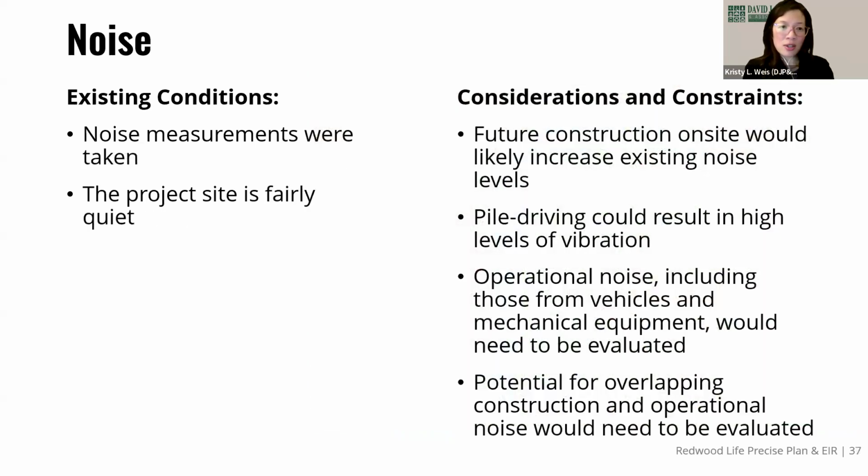For considerations and constraints, future construction on site would likely increase ambient noise levels in the project area. To reduce potential construction noise impacting nearby residents, best management practices for construction noise control, and potentially temporary noise barriers during the noisier phases of construction may be required.